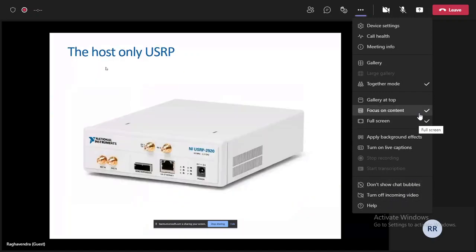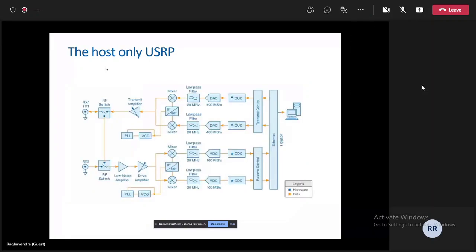So here, if you see, I told you that the actual carrier frequency is generated by the PLL plus VCO, which is correct. The output of your PLL plus VCO will be giving you a carrier signal, which will then be multiplied to your I and your Q. If you remember from the IQ architecture, we have two separate streams of data before they are combined and sent to the RF port. So the PLL plus VCO does the actual generation of the carrier signal.